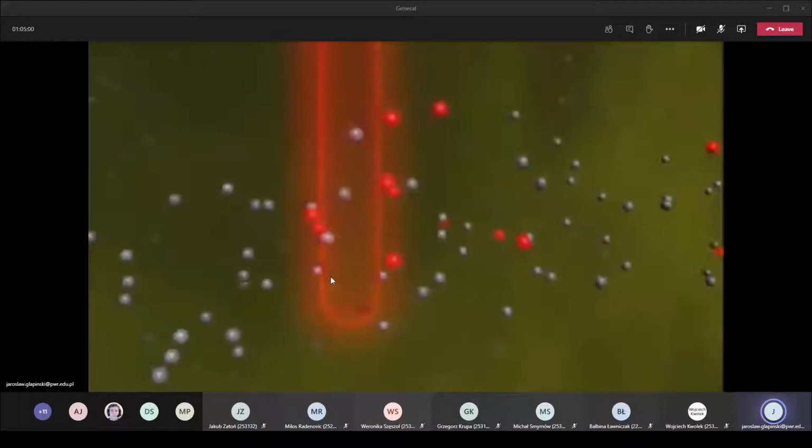The heat transfer also depends on the density of the gas because at a higher pressure or lower temperature, there are more gas molecules in the pipeline. The greater number of molecules results in more contact with the heated sensor, meaning increased cooling and thus increased heating current flow.